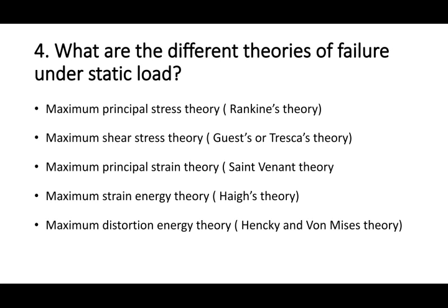Next question, what are the different theories of failure under static load? Number one, maximum principal stress theory, which is also known as Rankine theory. Then maximum shear stress theory, that is Guest or Tresca theory. Then maximum principal strain theory, that is Saint Venant theory. Then maximum strain energy theory, which is also known as Haigh theory. Then maximum distortion energy theory, which is also known as von Mises theory.